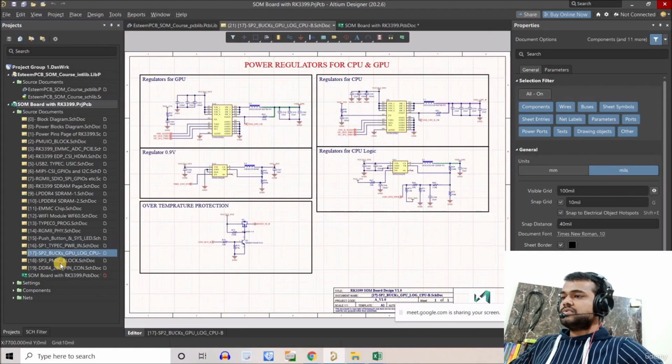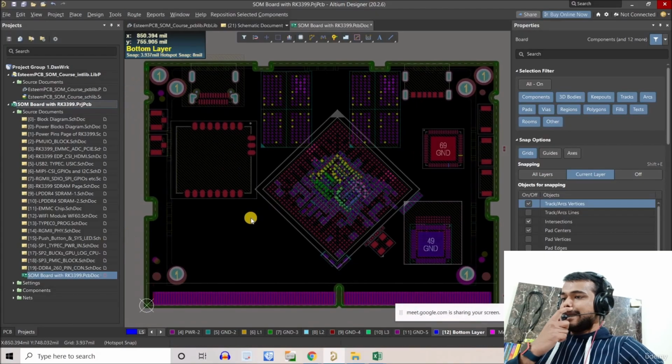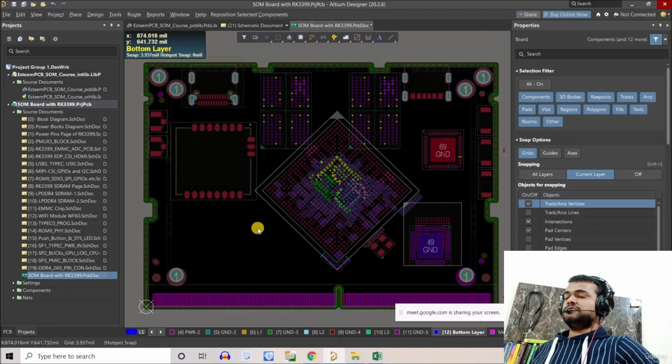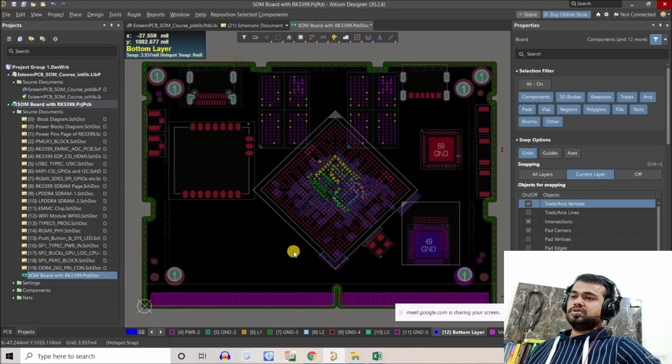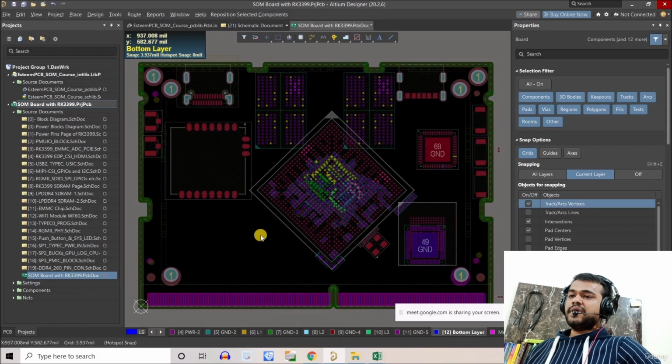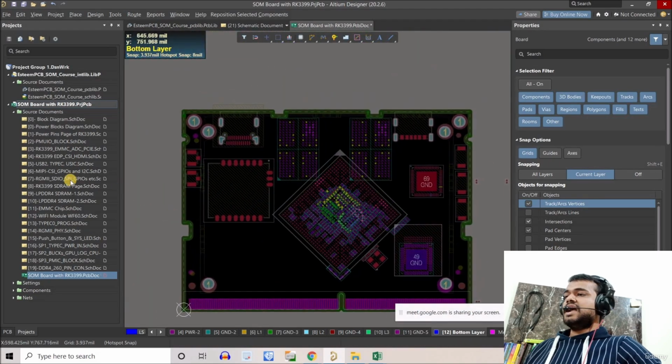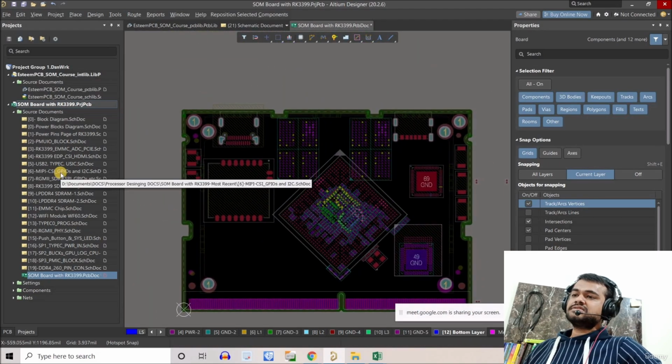So that's it, and these are the changes I did. Today, when I'll be sharing the video or the recording of the whole session, I'll just share this document as well, so you can compare if you did assignment number 6. You can compare your placement of the components, whatever components you placed on the bottom, and if you tried these net classes, you can see my thought process about these net classes and what you did. So whatever is better, you can just go for that.